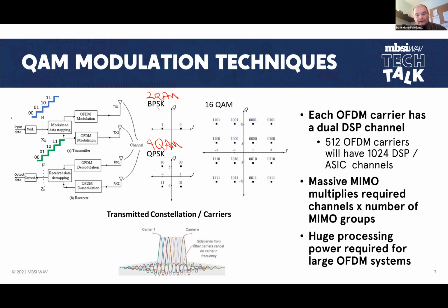If data, let's say 0010, was presented to my circuit here, when I split them, 00 would go to 1 level shifter, 10 would go to a 2nd level shifter, and then what this does is comes out with actually a DC voltage. So 00 would be here, 10 would be here. This DC voltage is applied to the modulator, which